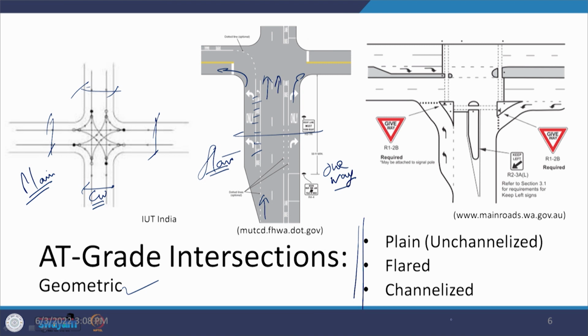Now, another thing which can be there: say the types of movements are increasing and we have to take care of that. So, what we have to do is go for channelization and look at what various types of road furniture need to be provided there. What you see here is an island, this is another island and that is another island. There is a median being provided on this side. There is a gap in this median, so that the pedestrians can cross using the crossing facilities.